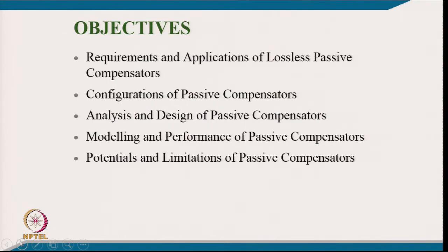The objective of today's presentation is the requirement and application of lossless passive compensators. We will talk about the configuration of passive shunt compensators and analyze and design these passive compensators. We will of course have modeling and performance of these passive compensators, and certainly the potential and limitations of passive compensators.